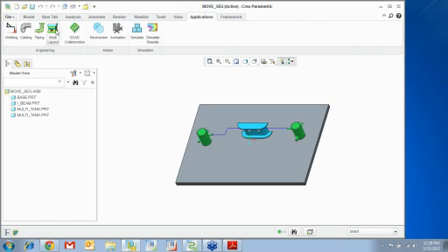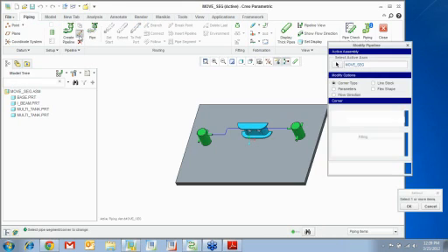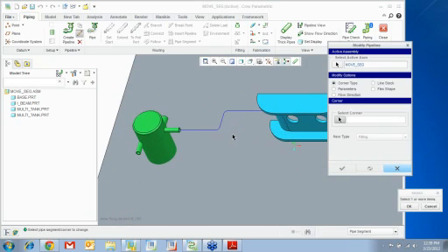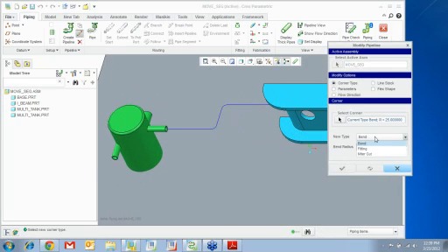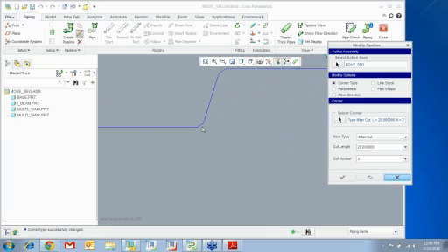Let's get into piping and let's edit a pipeline. You see that right there, corner type, say okay. You see that it's a bend. I can say I want to have a miter, and I want to have 2 miters with a cut length. You can see right here, see that, 2 miters,